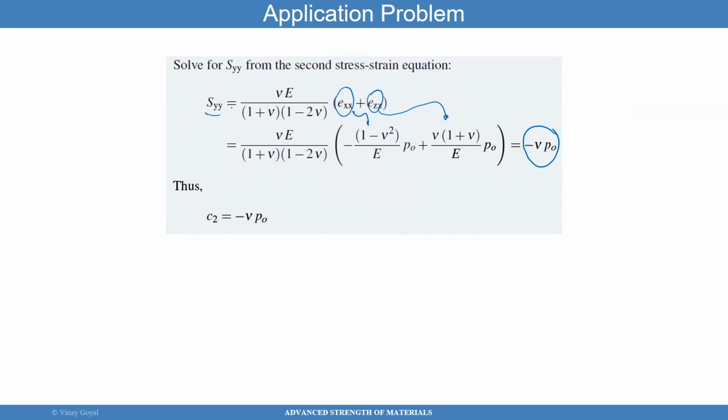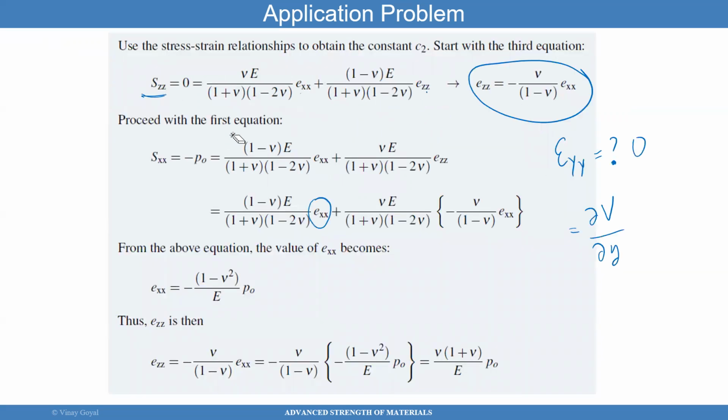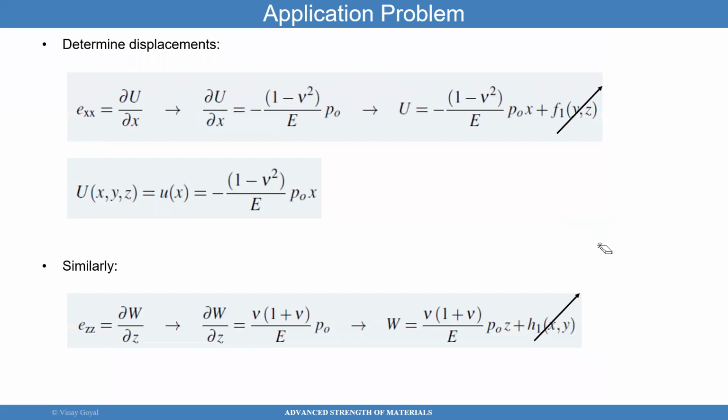So you pretty much know the stresses on that block, and you can predict failure of that block just with the information that was provided here, right? So I had the 3 equilibrium equations, I used the constitutive law, and I used the strain deflection relationships to make that happen. I can then calculate deflections, and that should be very easy. I know what the strain is because I found it earlier.